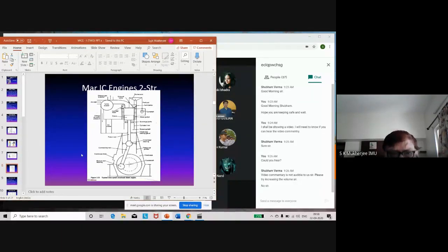So based on these, you get lubrication of the bottom end bearing, the main bearing, and the crosshead bearing at the crosshead pins. Now, lubrication on the guides is a little different matter. These are sliding bearings. Similarly, lubrication of the piston ring on the cylinder liner is not where you get hydrodynamic lubrication. An attempt is made towards hydrodynamic lubrication by profiling the edges of the piston ring, which will give it a wedge form. But that comes a little later. That comes in your lubrication chapter.